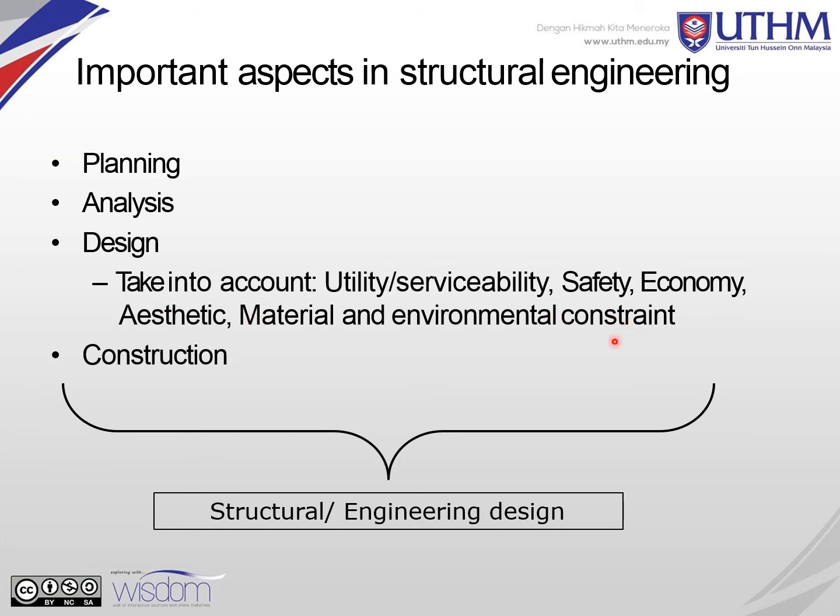When you do the design in another subject, structural design, you need to consider serviceability and the safety factor to provide more safety, and also economical design, to not over design and to save the cost of materials. It must also have a nice aesthetic view, suitable materials, and meet environmental constraints. After the design stage, it will go to the construction stage. So these are the important aspects in structural engineering.